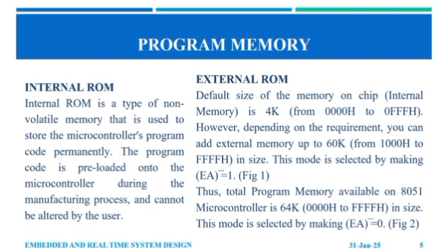We'll look at the internal ROM. Basically, the internal ROM is a non-volatile memory that is used to store the microcontroller program permanently. The size of the internal ROM is 4 kilobytes, and the addressing is from 0000H to 0FFFH.